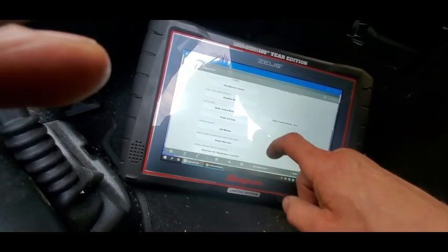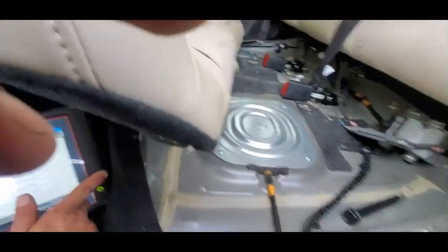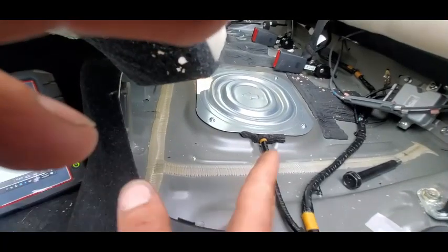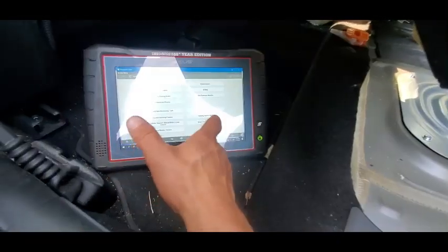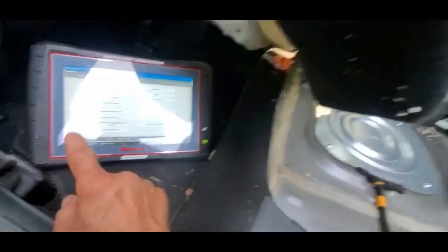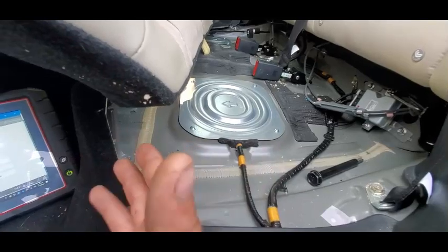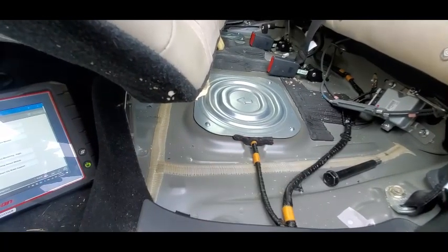So that computer is controlling that pump. Now I don't know, again, if I turn it on, is it going to be a 100% duty command? In either case, we know that when we were cranking it, that computer was, according to the scan tool, commanding it at 95%. So that should be pretty good. If we do a crank, we'll just get an assistant and then we'll get our capture, okay?